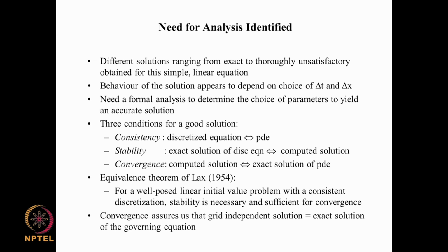that the solution that we are testing is equally sensitive to all changes in delta x and delta t. Okay. So, for example, if we solve for the temperature variation and deduce from that a heat transfer coefficient, the heat transfer coefficient is obtained from the gradient at the boundaries. So, the gradient at the boundaries may be either less sensitive or more sensitive than the temperature at a particular location within the domain. Okay.